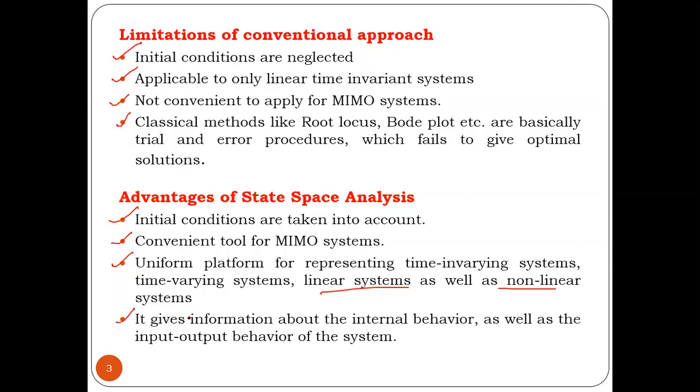The next advantage is that it gives information about the internal behavior as well as the input output behavior of the system. Through the transfer function you get the input output relation. Internal behavior means, at each node, what the state condition is. That can also be determined using state space analysis. When you have a circuit, in the transfer function domain we calculate what the output is for a given input.